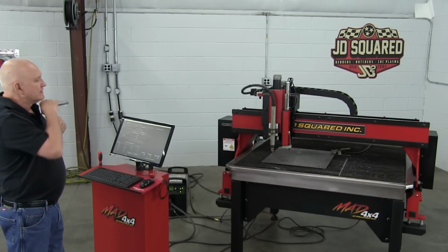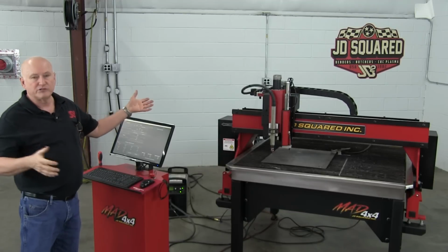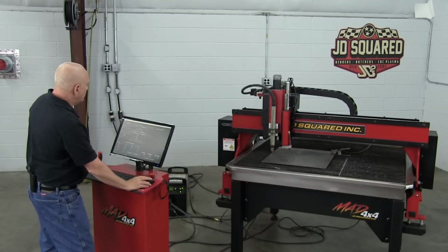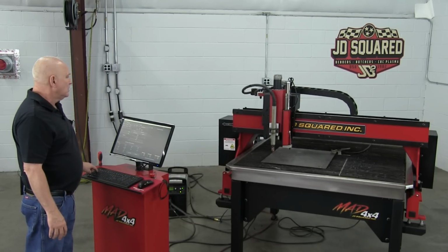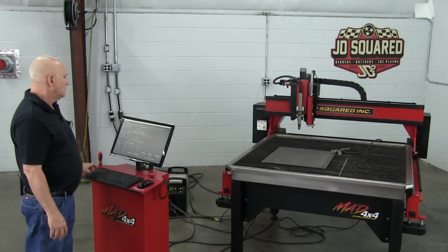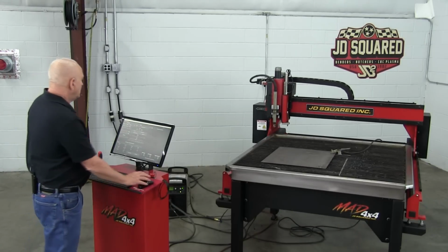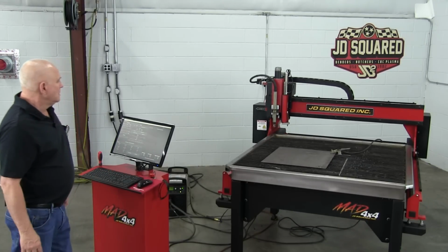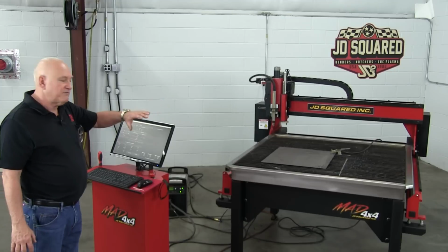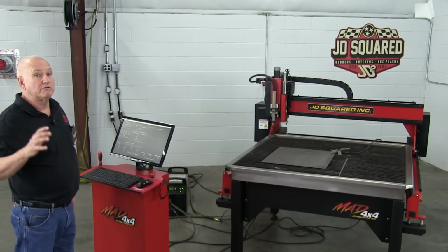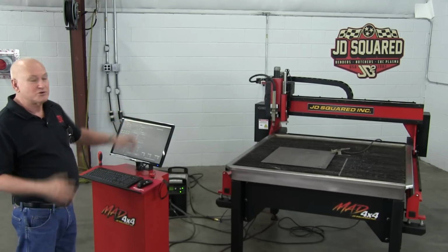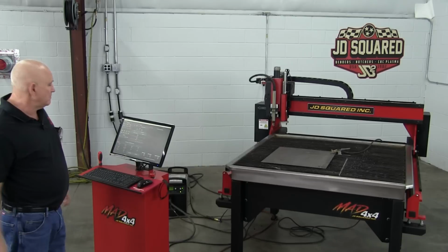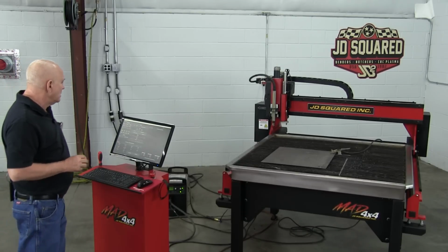First thing we're going to do, the machine is obviously starting at a raw state. Like in video 1, we're going to turn on the drives, and we are going to do the home cheat that I showed you how to do earlier. And we're going to hit the home all button. Remember, I could cheat by homing Z first, and then I could wrap the machine around. However, there is a crash hazard, so I was very careful when I was wrapping it up not to let the machine crash. But it did decrease the time that it took me to home the machine. Okay, here we go.